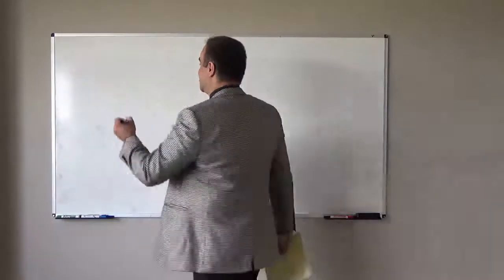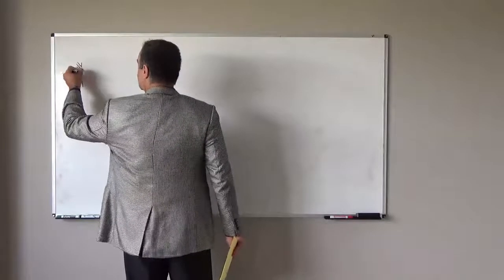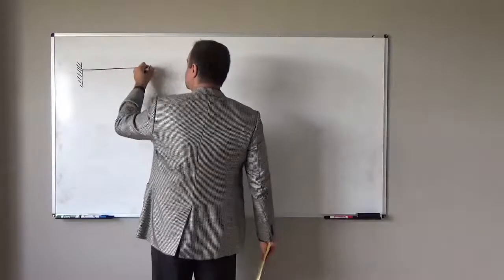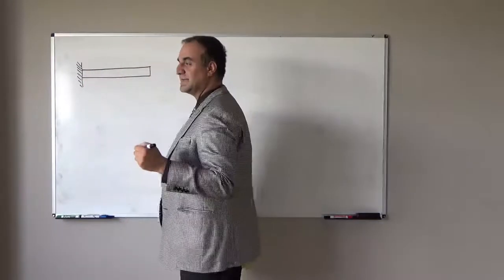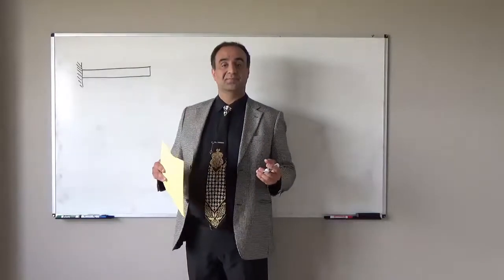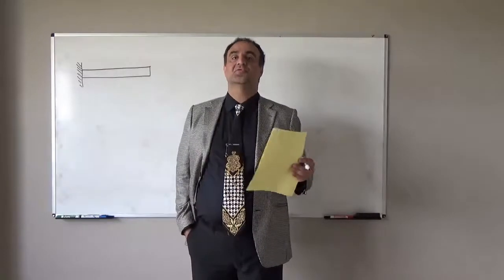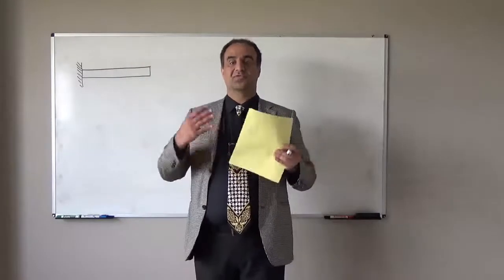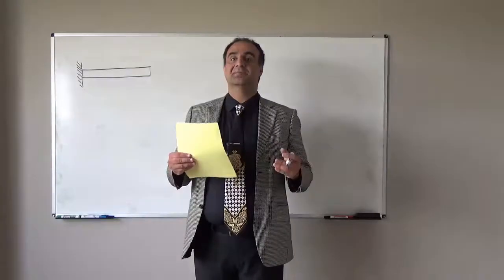If you remember, as I mentioned, if we have one rod or any type of structure, if we increase the temperature, we will have expansion. If we decrease the temperature from room temperature, we will have contraction. And for any type of structure, for example this rod, once it is free to move, free to deform, we will see deformation, but we will not have any internal force or stress. Stress or internal force as a result of the temperature change is equal to 0.